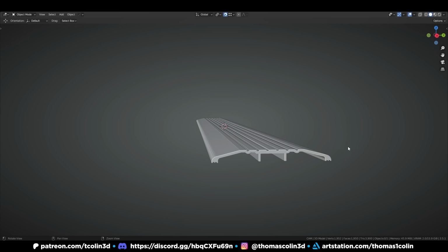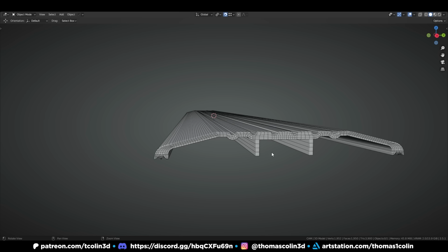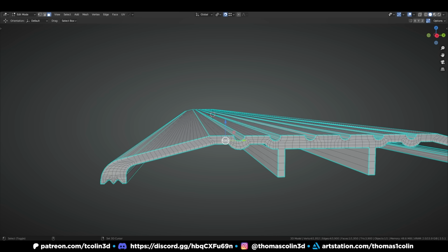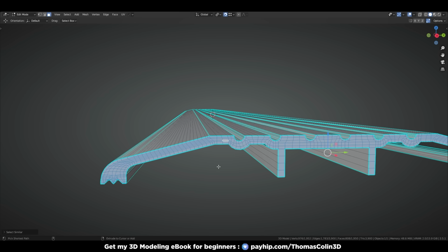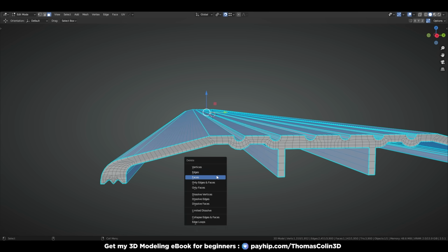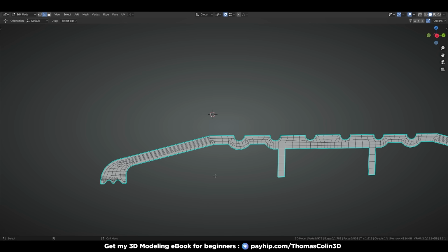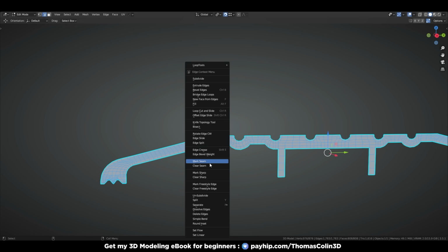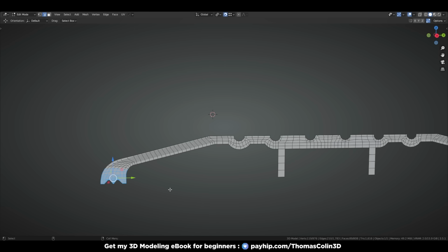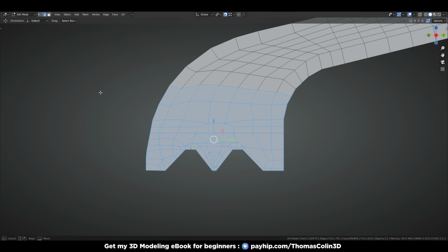To begin with, I'm only going to keep the profile of the mesh. I'm going to isolate it by selecting one face, press Shift G and choose Coplanar. This will select all the flat faces on the same axis. Then I press Ctrl I to invert the selection and delete the faces. For practical reasons, I'm going to remove the mark sharp effect because the blue edges are visually distracting. Now that everything is ready, let's zoom in a bit and analyze what's wrong.